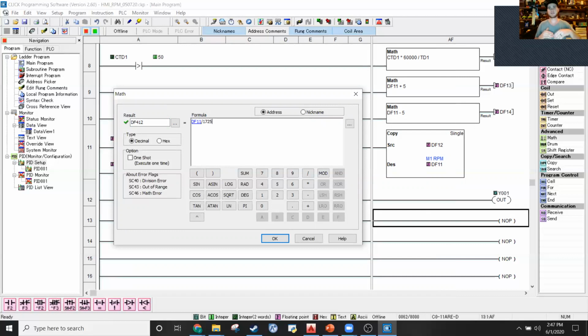And so what this is doing is it's taking my measurement and dividing by my max, that's a percentage, right? And so this should range from 0 to 100, although we just talked about how it's going to go slightly over 100 because our motor spins too fast. I didn't do the math, I just made it 110% on the max bound because I know that's way more than we are over. Off the top of my head, it's like 1 or 2% over 100.